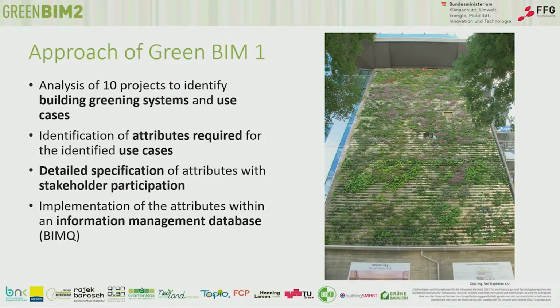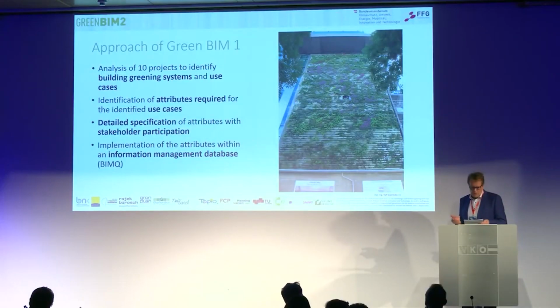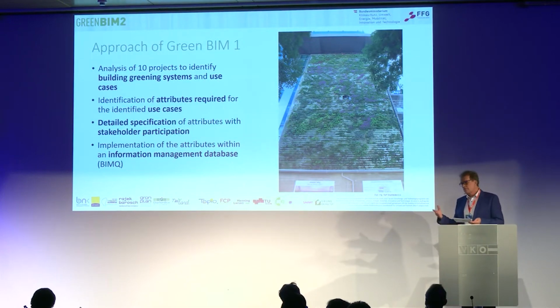Following that, they were implemented within the information management database BIMQ. After the implementation of the attributes in BIMQ, they were mapped to IFC and BSDD, the Building Smart Data Dictionary, and structured so that they can be used as intended according to the use cases identified before.